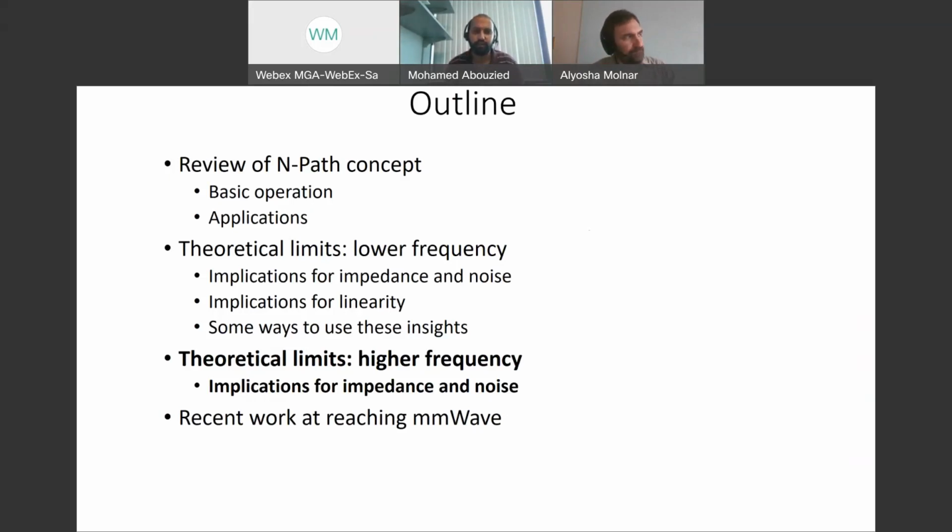In terms of magnitude and phase, is there any delay that is being introduced with the system, assuming that we have very sharp edges? Right. There's not really delay because the behavior you see on the RF port is essentially a closed loop behavior. There's essentially feedback going on between the baseband and the RF port. So both the baseband and the RF port are caught in that feedback behavior. The feedback is just through the resistances, but it's there. And so they're reasonably well synchronized. You don't see a phase shift delay per se.